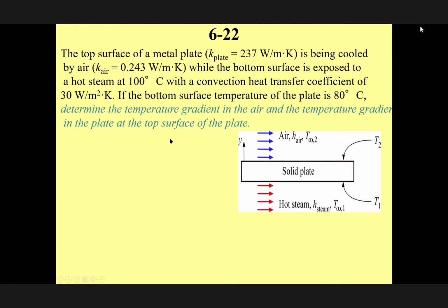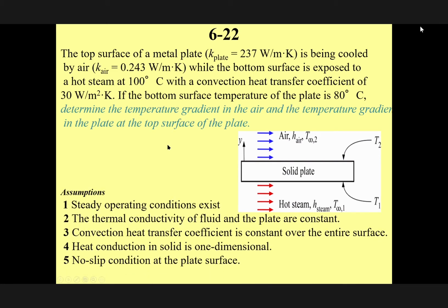We mentioned this first. Whenever we like to solve any problem, we make a set of assumptions, and one of the reasons this is very important is that the equations we are using are based on certain assumptions. Therefore, that solution is only correct for those given assumptions. One of the assumptions we made in the development was a steady operating condition. It means the boundary conditions will not change.